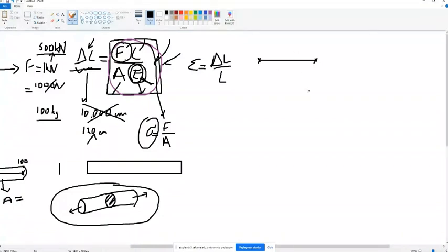So these are basics, but instead of solid, I can make it simpler using a line element. Creating a line element, maybe I don't want to discretize the element, just one element. So discretize into two, one and second element. Discretize it into four, one, two, three, and fourth element.